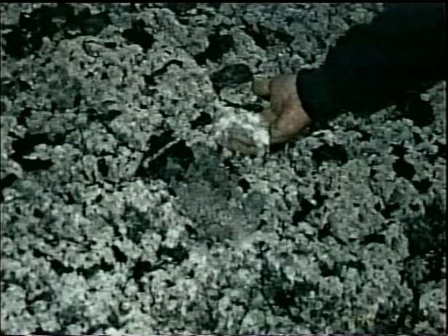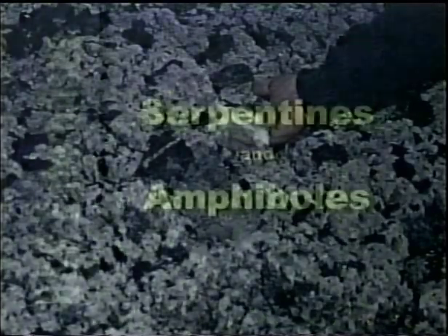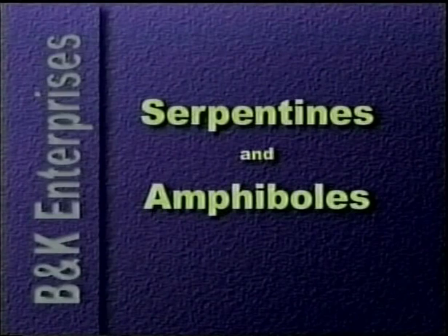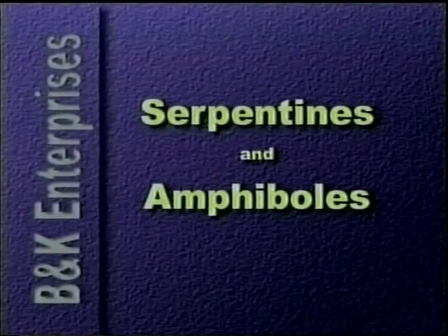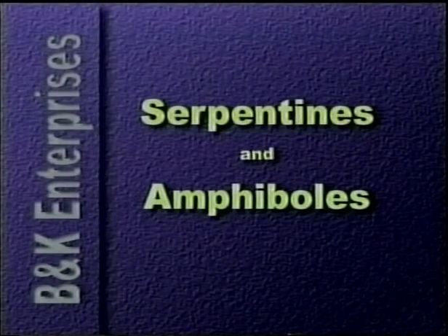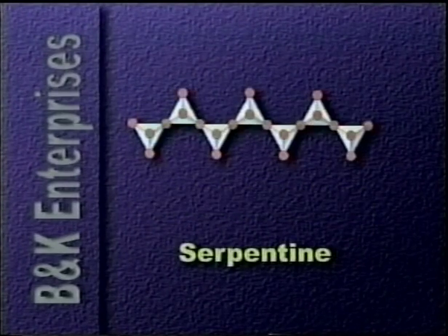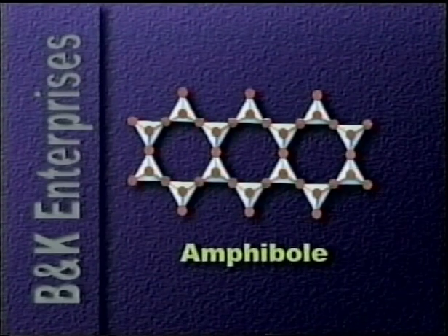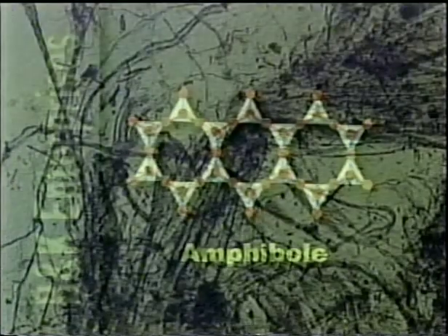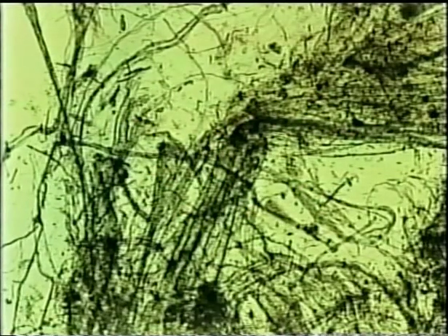There are two broad categories of asbestos materials: serpentines and amphiboles. These terms describe the molecular configuration of the material. In the serpentine group, the molecules are connected in long lines. In the amphibole group, the molecules are interconnected in a bowl shape. Under magnification, the minerals in the serpentine group look like long, wavy bundles of material. Those in the amphibole group look like needles.